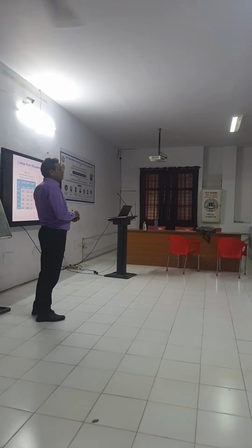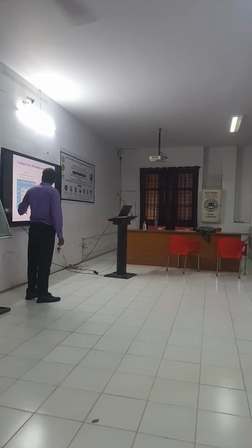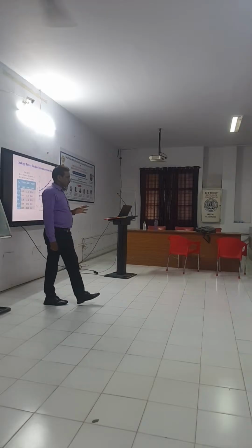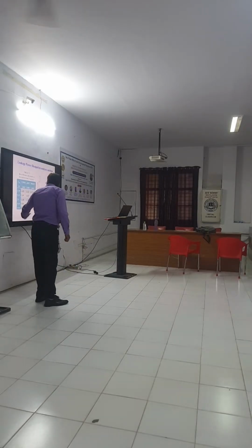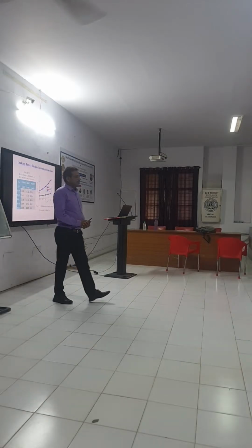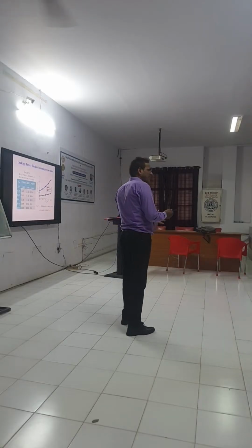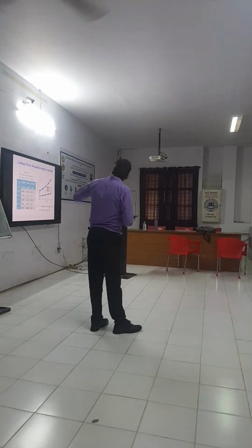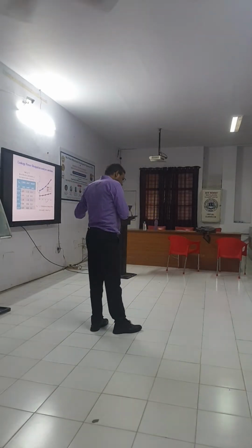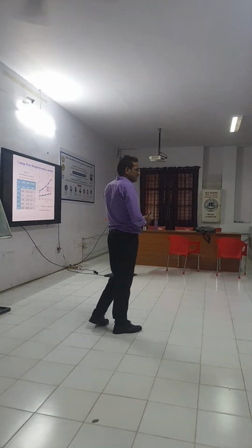So in simulation, we calculate and see for conventional leakage power 1.89 at 0.44 volt. Similarly, at the current supply voltage for this conventional zigzag gate and proposed. Again, what we are getting, our proposed one is showing lower leakage power as compared to this. Here I compared only two circuits. You can compare 5-6 other circuits. Then it will be good. Getting it? Okay.